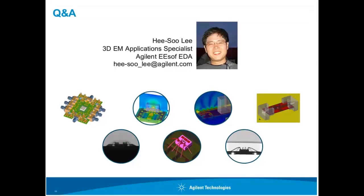This goes back to the measurements, Hisu. You talked about calibration methods. A question from Scott is, which calibration method did you use for the 50 gigahertz measurements? Basically we used the eCal, electrical calibration, to measure the structure of this QFN as well as the Thru line up to basically 65 gig.